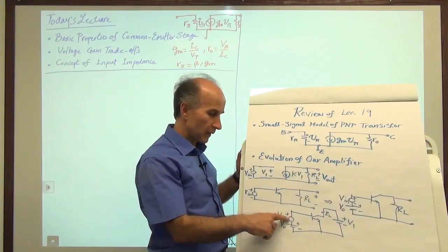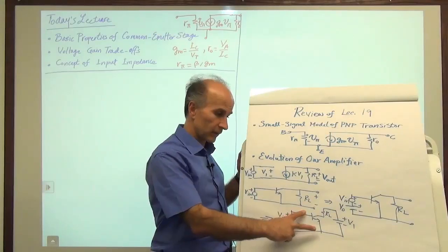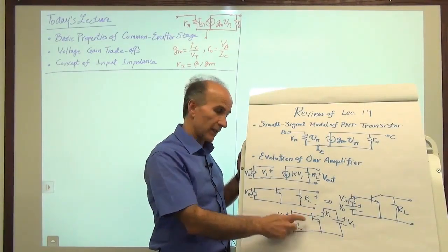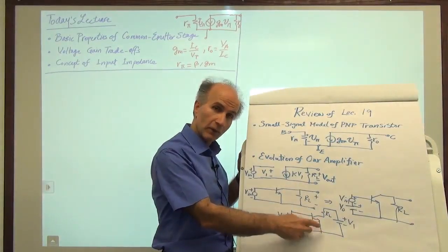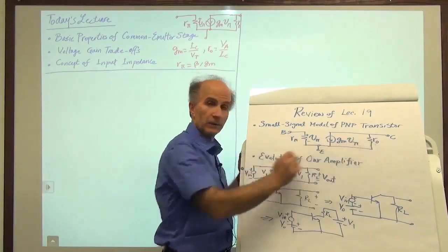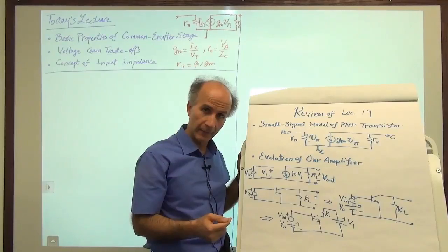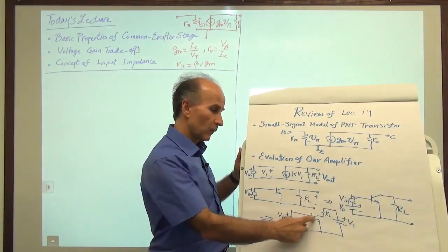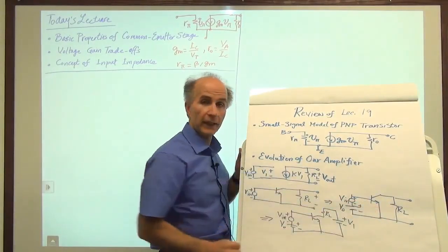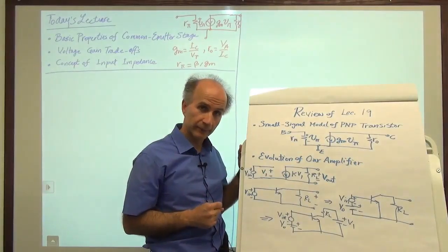Then we placed the microphone signal in series with a battery and applied the result to the base-emitter, hoping that the battery would establish a certain bias current to give this device proper values for g_m, r_pi, and r_O, because these all depend upon I_C, the collector current. And then we let the current flow through R_L, and that was what we thought would be a good amplifier.